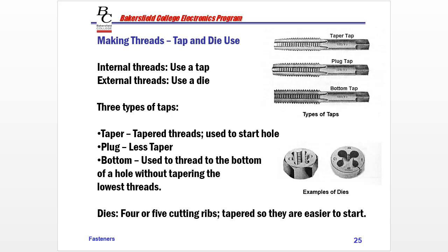It's very important that we use the proper drill bit size to bore the hole in the material that matches the tap size that we're going to use, or else it will be very difficult to cut the threads if the hole is not big enough, or we won't cut the threads deep enough if the hole we drill is too big. So don't just eye it, look at the chart and make sure you use the proper hole size.